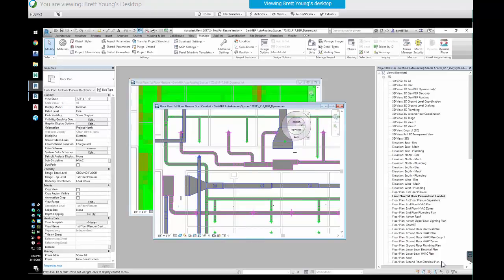So if the architect has raised ceilings in certain areas, does this detect it? Right now it's really manual, but yes, it could. The bottom bounding of those columns can be changed, and should be changed, for different ceiling heights.